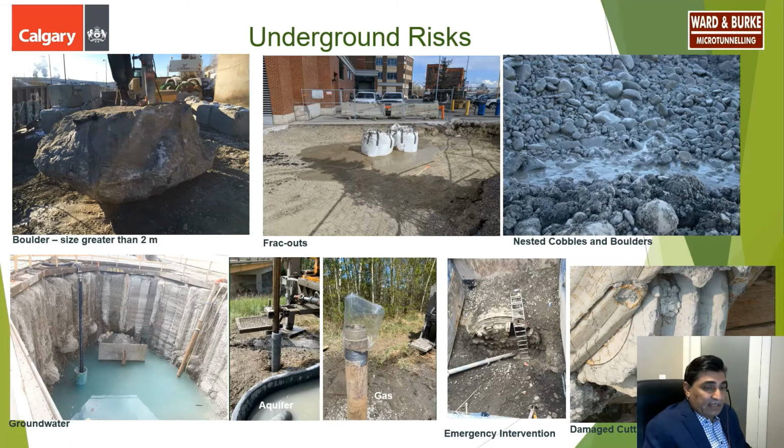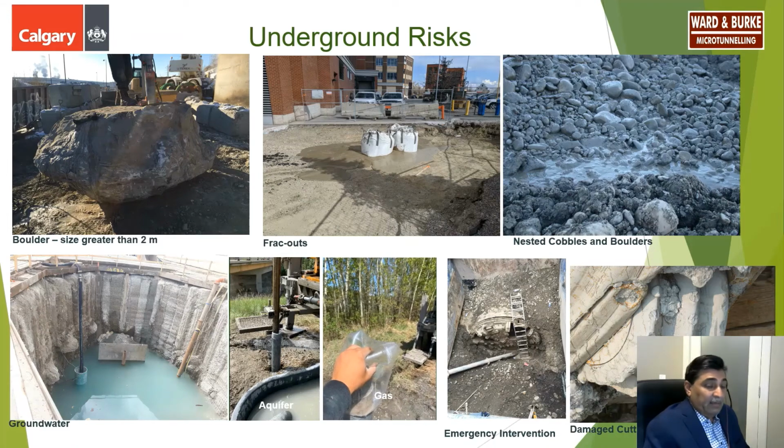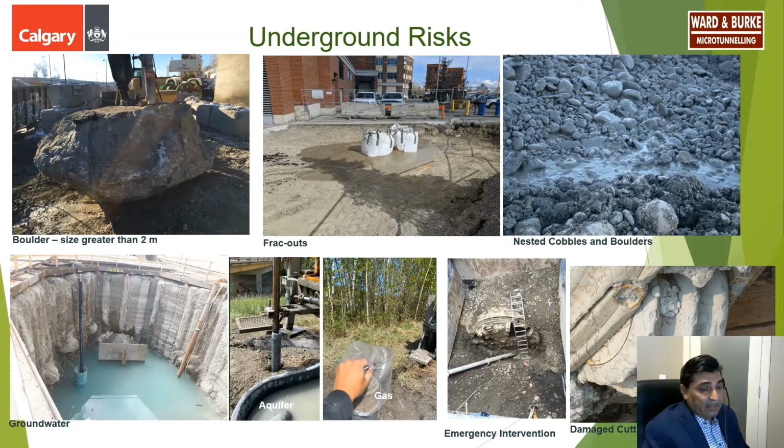So we have to characterize if there are any aquifers. Sometimes there are gas pockets in the ground as well, and we have to characterize gas because if there are gases in the ground, we have to inform the contractor. So if we are in difficult ground conditions and we have not baselined the ground conditions properly, there could be damage to the MTBM. Or if the contractor has not brought the TBM according to baseline conditions, then the TBM could be damaged. Then we have to decide who will pay the cost of repairing this TBM. In this case, you can see the TBM was damaged because of boulders, so they had to do emergency intervention and repair the MTBM.